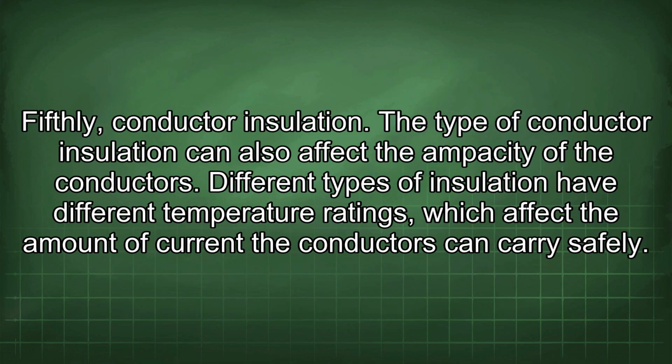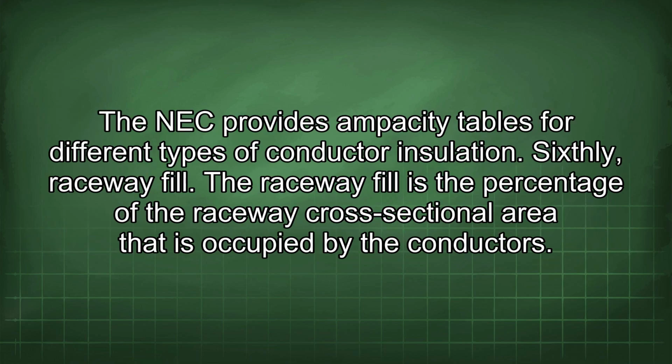Fifthly, conductor insulation. The type of conductor insulation can also affect the ampacity of the conductors. Different types of insulation have different temperature ratings, which affect the amount of current the conductors can carry safely. The NEC provides ampacity tables for different types of conductor insulation.